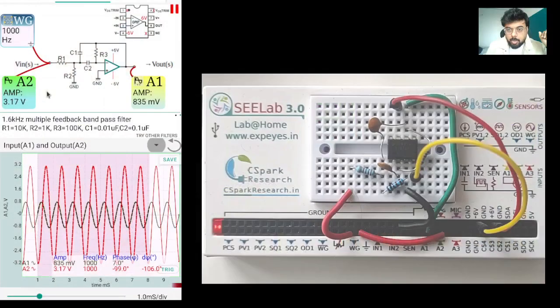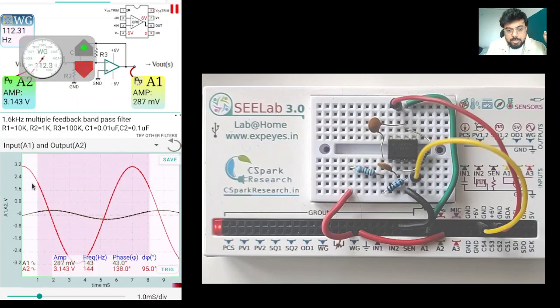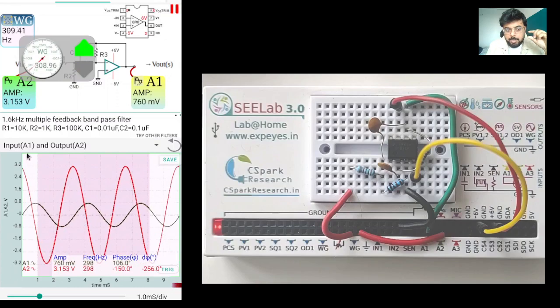So let's switch to the plot view. As you can see here, the black trace represents A1, which is your output from the filter, and the red trace, which will be fairly consistent throughout the experiment, represents the input given to the filter. Now let's see what happens when you change the frequency. Let's start from a small frequency, say 150 Hertz. You see the black trace is smaller. The output is smaller than the input.